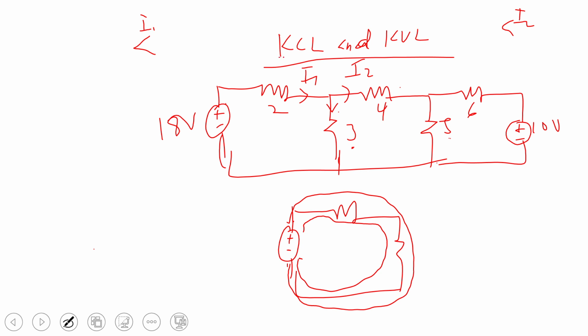You have to apply the Kirchhoff current law in the process of assigning current within the circuit. So now, we could see from the class on Kirchhoff current law and Kirchhoff voltage law that if I have this node or this junction here, and I have the current here as I1 and here as I2, then I don't need to call here I3 because I just have a junction where I am aware it's three things there, I1 and I2. The third one can easily be found using the Kirchhoff current law.